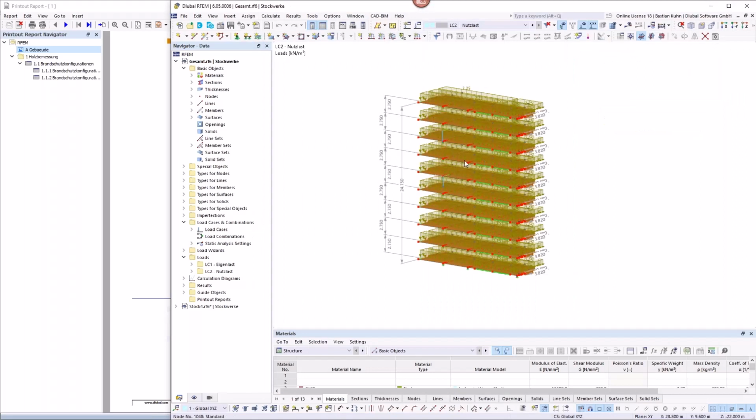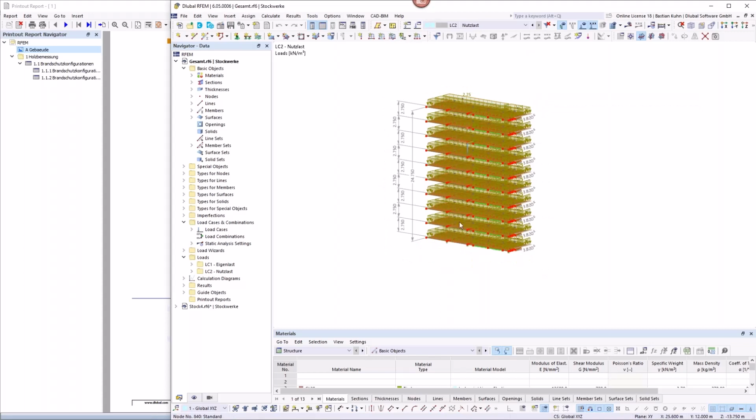As I said, I want to calculate that in a 2D structure, but with 3D effects. Therefore, just to give you an imagination of the structure, I just copied the top stories 4 to 13 in a separate position, that I make a simplified load case there for the self weight 4 kilonewton per square meter, and the live load 2.25 kilonewton per square meter in each story.